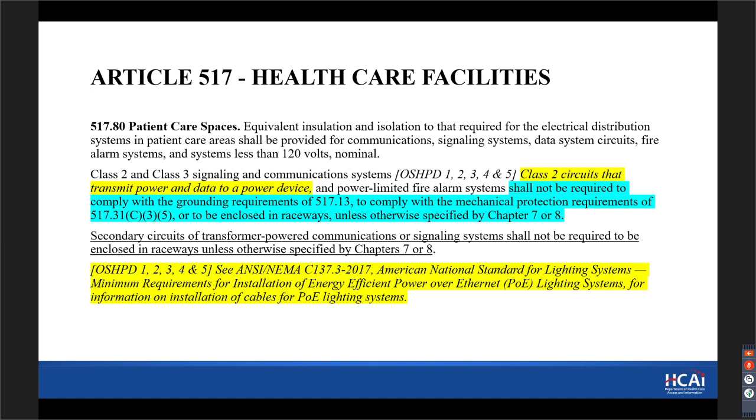Last question reads, are light switches and receptacles connected to the equipment branch in hospitals still allowed to be red in color, similar to the life safety and critical branch? Yes, they're allowed, but they're not required.